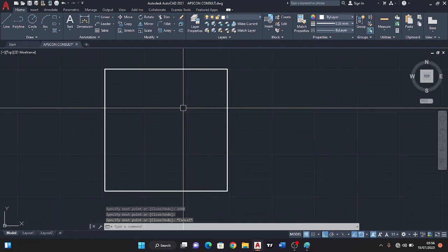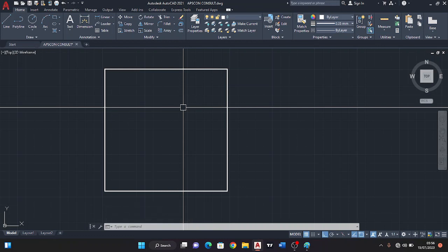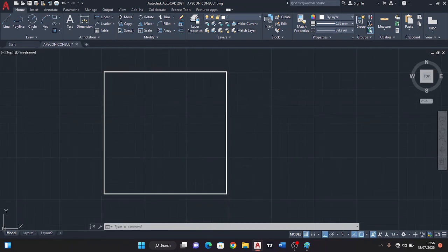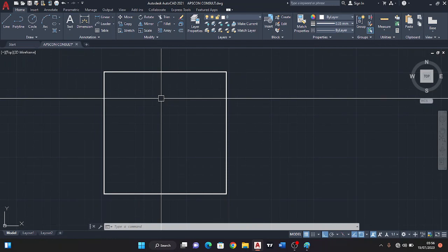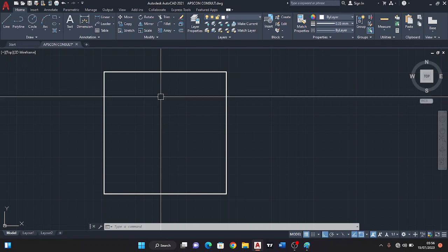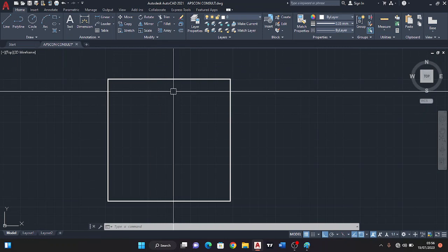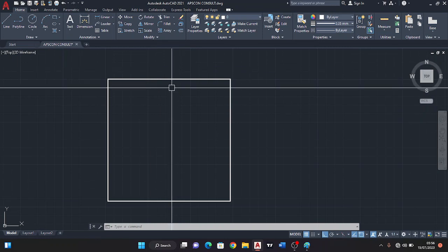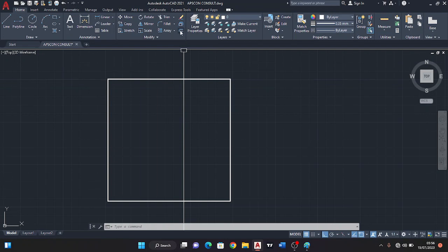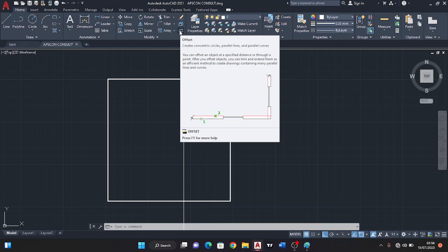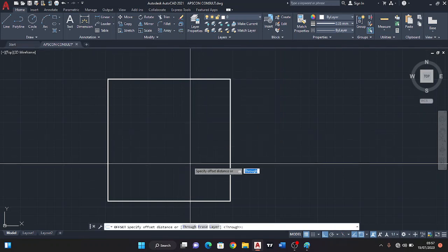Now there are some basic things you need to know, like the size of the block you are using, the height of your building, the height of your DPC, the damp proof course, the height of your window, the width, all those things. Now let's start with the thickness of the block we are going to use for this building. Since it's a residential house and there's no story on it, we're going to use our partition block, which is 6 inches. Now that 6 inches is 150 mm.